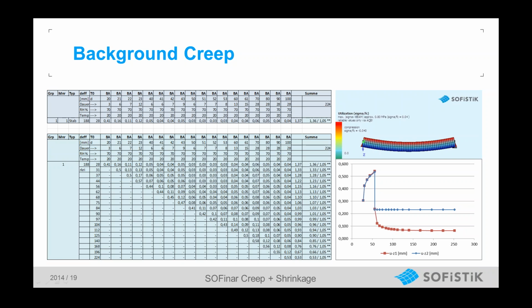In the second table, the lower part, you see we have exactly the same creep values, the development of the creep values, but we also have the output of the relief creep or the real creep effects. That means what happens after we unload our system.